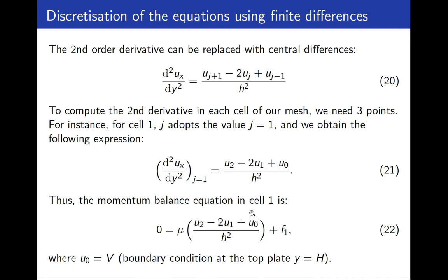So, discretization of the equations using finite difference. By discretization, I mean that the purpose of any discretization technique is to transform one or more partial differential equations into a corresponding system of algebraic equations. And the solution of this system will produce a set of values which correspond to the solution of the original equation at some predetermined locations in space and time.